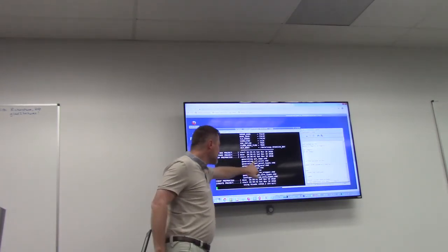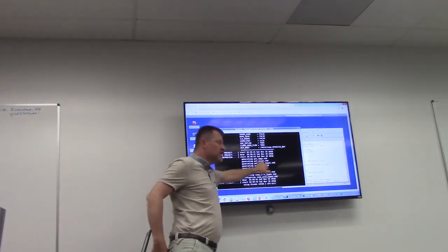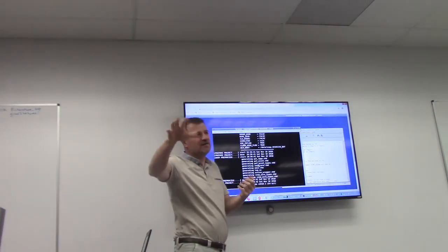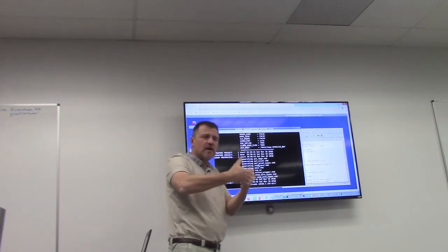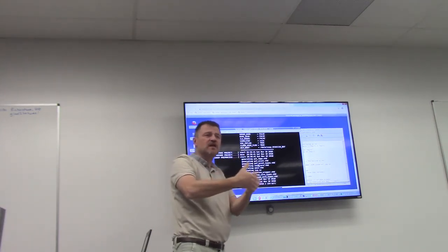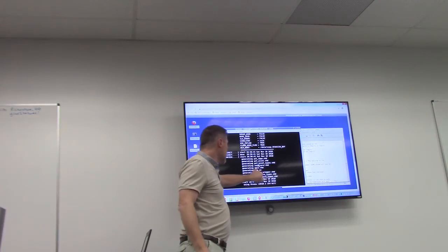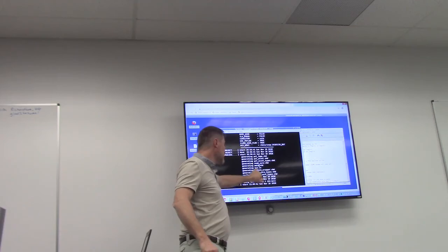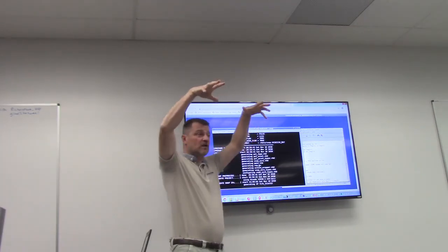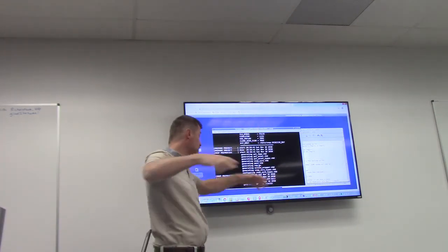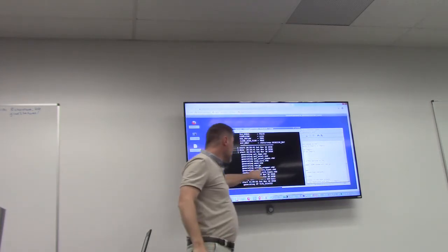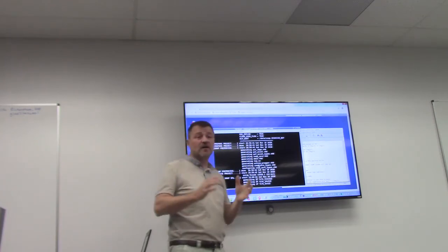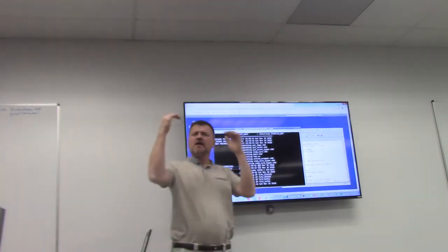It generates, for example, the FPGA PSL to FPGA connection. The FPGA side that is for the user is connecting to the PSL, the blue logic that talks to the computer. It creates the MMIO where we store the information for the register. It creates a top file, that's for the hardware engineer, the top description of the complete FPGA, including all the pins and so on. It puts all the wrappers, and that's nice because every time it puts that, he has a source file, and he says, do I have a DDR memory?